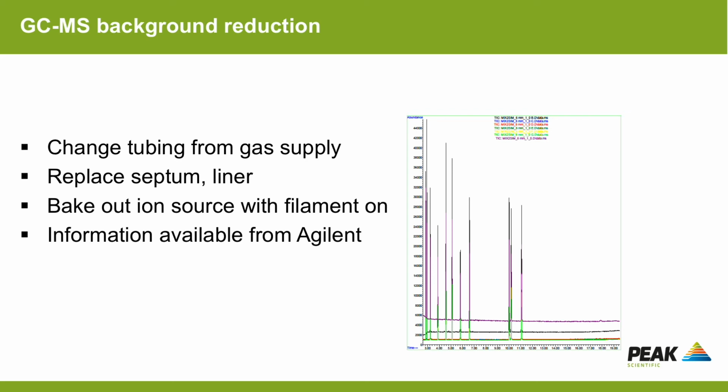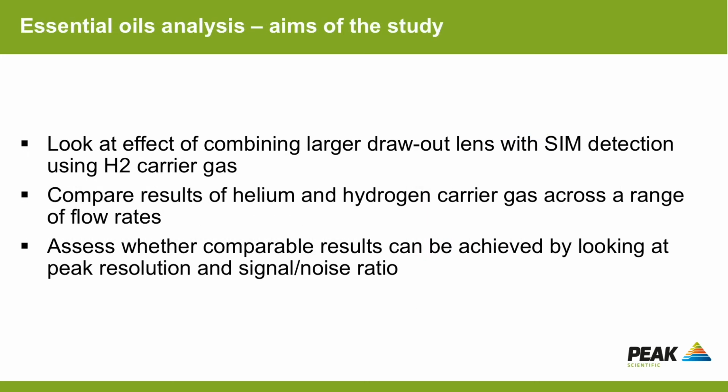So on to the actual analysis and the aims of this study. We did this in collaboration with a university in Sao Paulo in Brazil, and we were interested in looking at the effect of combining a larger draw-out lens, which is the component in the ion source of Agilent GCMS single quads, and looking at SIM detection, so selected ion monitoring detection.